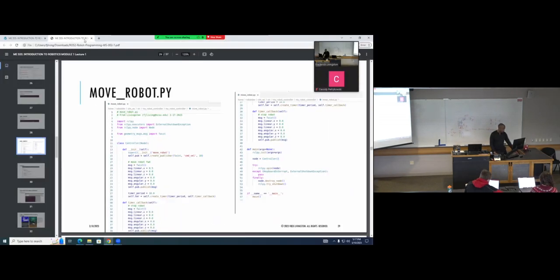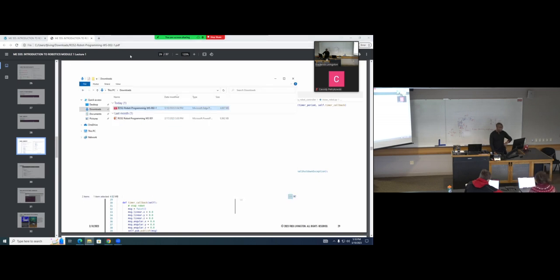But if we go to, there's a slightly different software that's running in the simulator than the actual one. What I showed you is kind of a reduced set of that, but the actual one you load there has the differential drive controller software that is taking that vector and saying, okay, motor 1 has a PWM signal of this, and motor 2 is this.